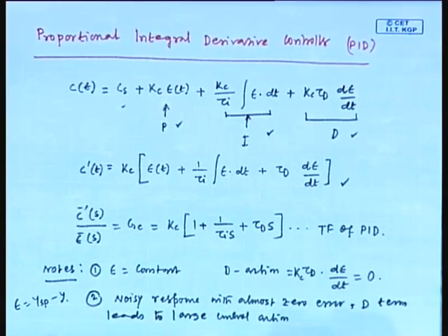So, we can say this is unnecessary. You can say this is a drawback. These two are drawbacks of PID controller. When error is constant, there is no action from derivative action, and when there is noisy error, the derivative action unnecessarily is large.